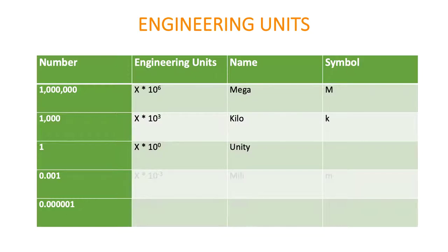The next one is times 10 to the 6, or mega. As the name implies and sounds, it is millions. So if we have megaohms, we have millions of ohms, and we use the capital M. Now here's the one that I found a lot of students have tripped over, the milli. Going back the other way now, milli is thousandths, times 10 to the minus 3.